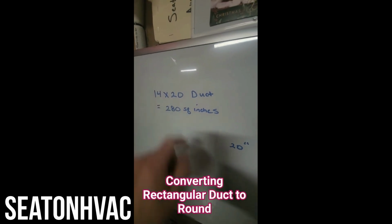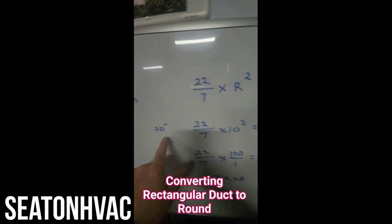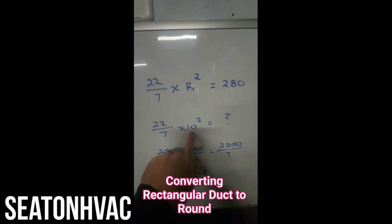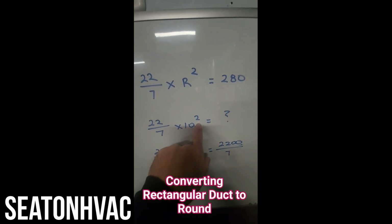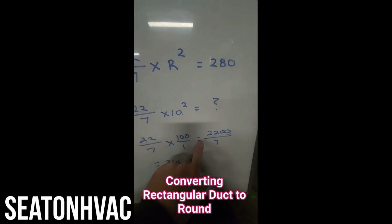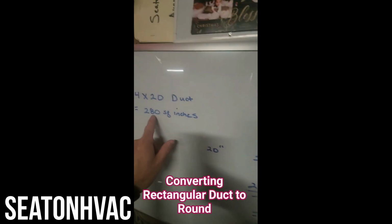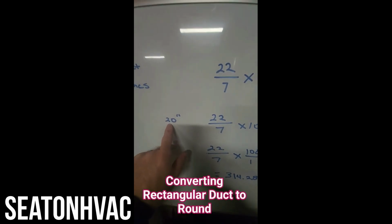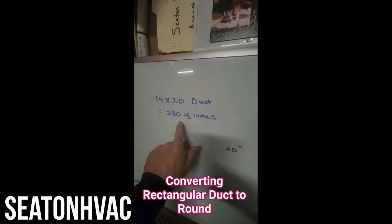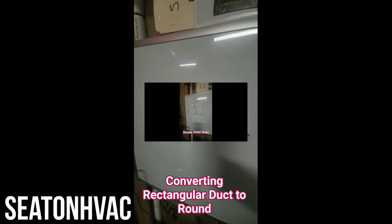All right, converting our 14 by 20 duct into round, 280 square inches. We went ahead and went with 20-inch, so we're pi times our 10 times 10, which gives you 22 over 7 times 100 over 1, 2200 over 7, 314. It's larger than that. They don't make 19-inch duct, so we're stuck with 20-inch. That's how we convert that 14 by 20 rectangular duct. Easy peasy. That's how you do it in the field.